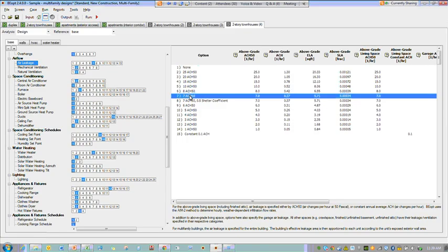And the unit geometry will also affect the wind speed, like how high off the ground the unit is, and the shelter coefficient is affected by the exposed surface area of each unit. So those are the things that go into the infiltration model for each unit. And we're certainly open to other suggestions or ways of doing this, but we think this works pretty well.